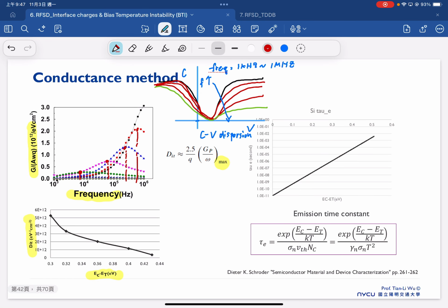So we are not only having this CV, actually this should be the CmV, because that's the real measured capacitance. That includes all of the ideal and non-ideal effects, where ideal means the oxide capacitance, and non-ideal means the influence coming from the interface state density.